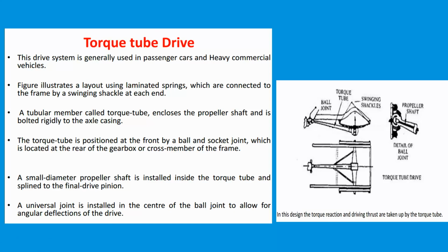The torque tube solves the problem by coupling the differential housing to the transmission housing, and therefore propels the car forward by pushing on the engine and then through the engine mount to the car frame, with the reverse happening during braking.